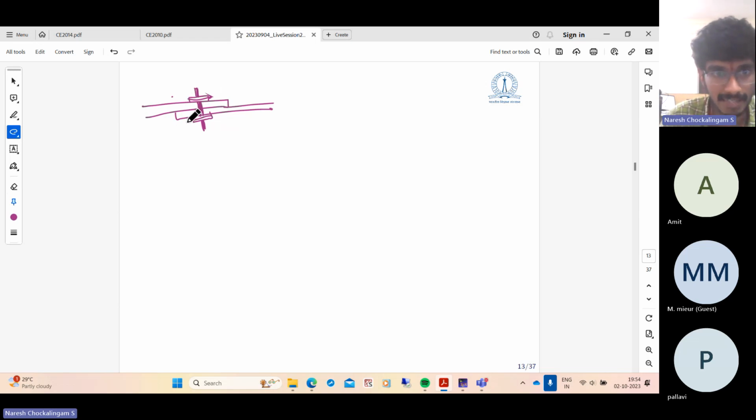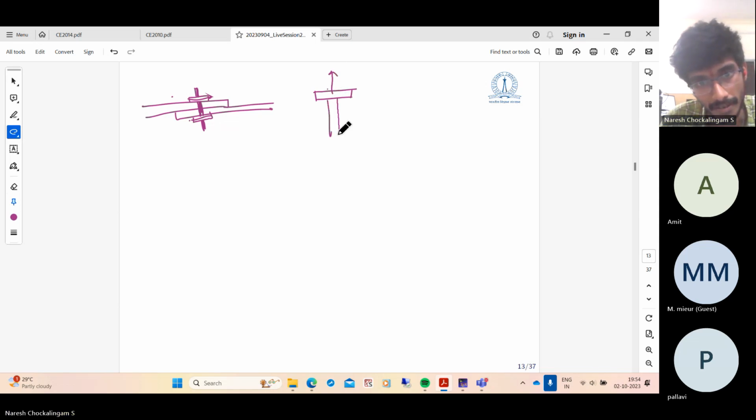if you tighten these extra, what happens is the bolt is subjected to a tension. So now if you draw the free body diagram, the bolt is subjected to tension. What happens as a result is that equal and opposite compression develops on the plates. So you tighten it and then you leave it. This is not an externally applied tension, right?